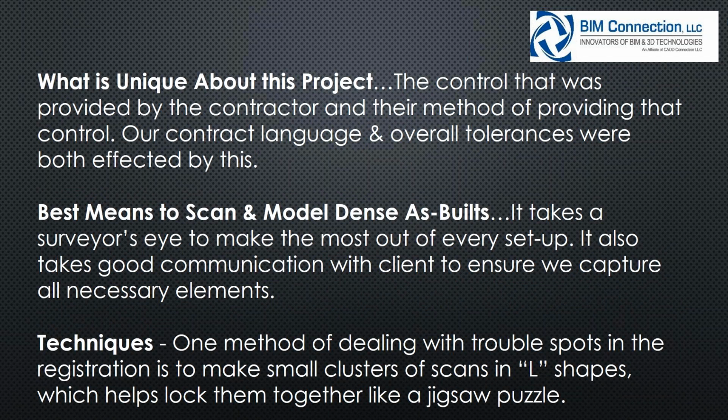Other than that, unique aspects of this project, the science project: the controls are provided by the contractor. We do feel that from a best practices standpoint, to have scanning completed from a surveyor's perspective is very important. It's very value added, and obviously basics such as good communication with the clients, as the requirements and deliverables, as we've all experienced, tend to change throughout the project. One technique we can comment on is when dealing with trouble spots, we tend to register in a way where we can make small clusters of scans in L shapes, and it helps lock the scan data together.